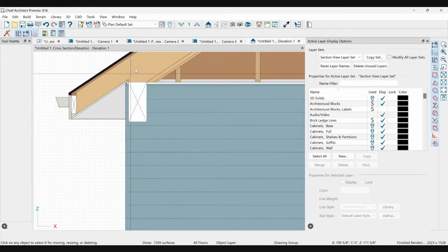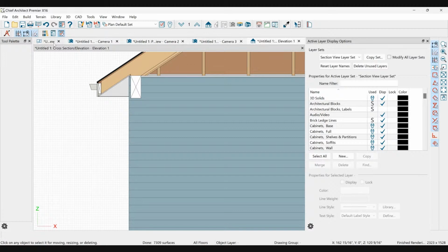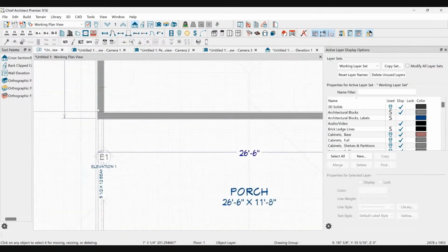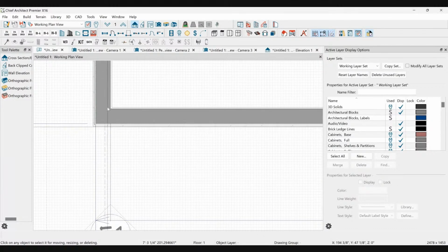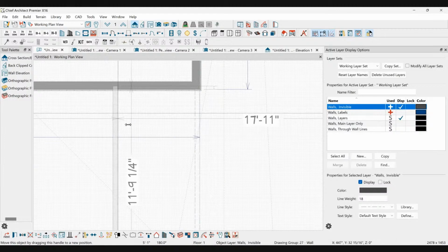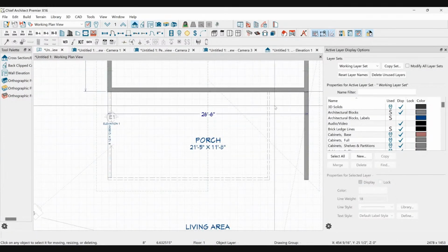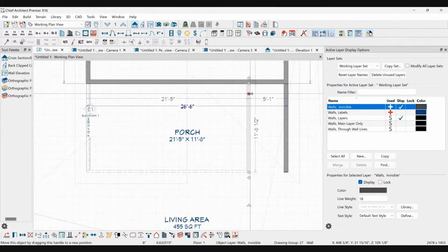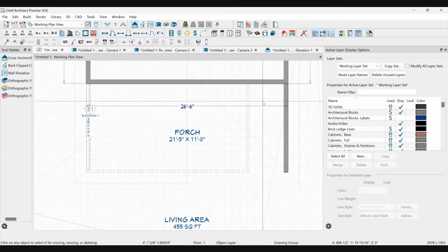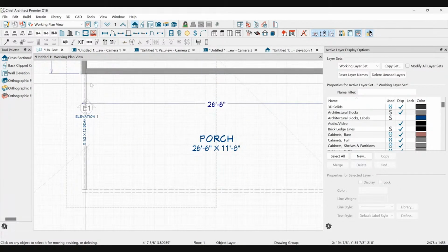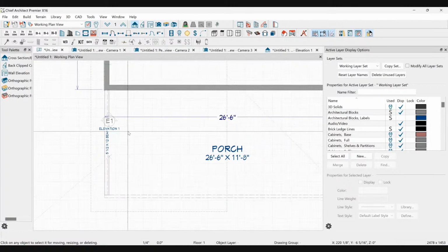And so the rafters basically don't care if they're sitting on a beam or the wall, they're cut the same way. And so knowing that, when you're doing porches, you want to pay attention to how this ties in, and you want to rely on existing wall geometry. Now, if we, for example, had the porch super narrow and it was way over here, then we wouldn't really care where we land it because it's going to land in the wall wherever. But that is not the case. So that is what we deal with when we're talking about beams and coming off of a wall here.